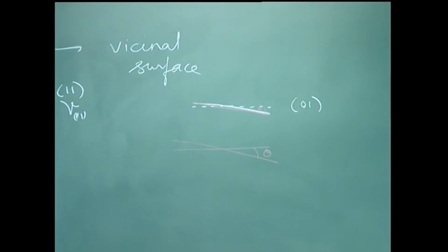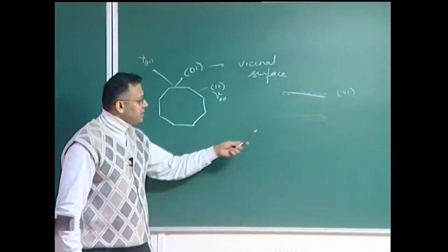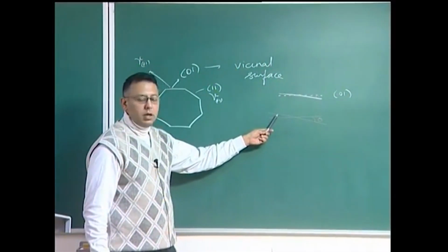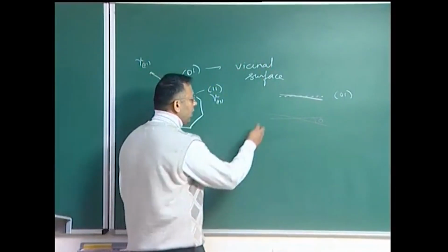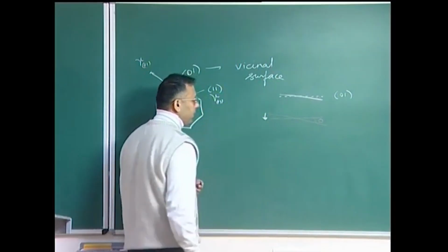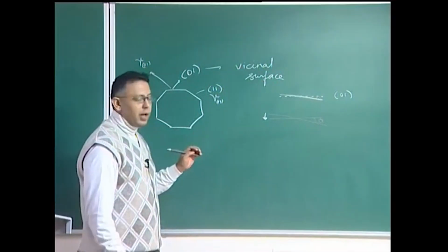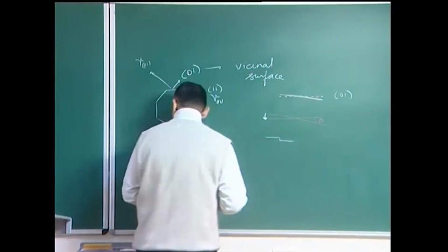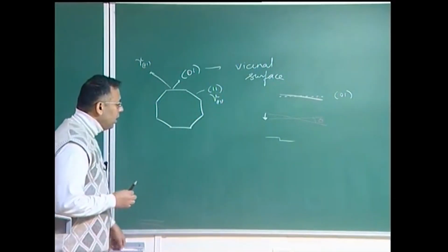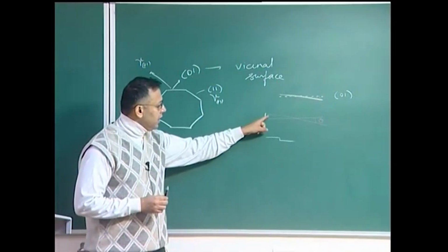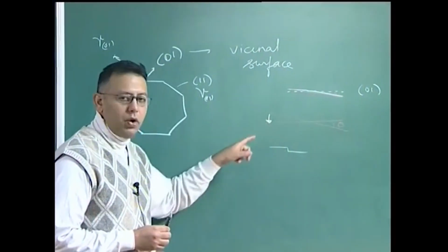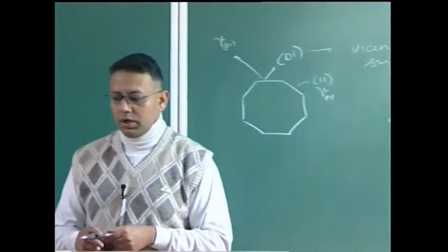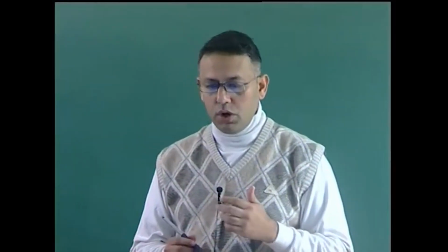Now, since these low index planes are expected to have higher density and they are also typically associated with lower energy, while these kind of high index planes would have higher energy, there is a tendency for this plane to rotate into this orientation. Of course, it really does not rotate, and typically you would find that this would actually break up into steps and terraces, but that is a detail we will not consider now. For now, I will note that this tendency for rotation to a low index direction or a low energy direction is the origin of what we may call the surface torque.